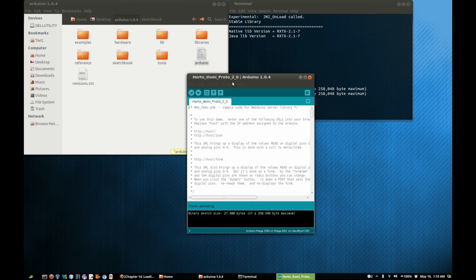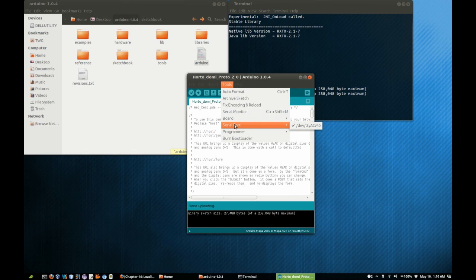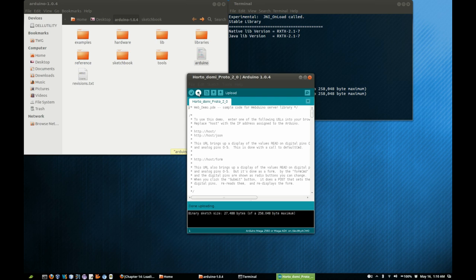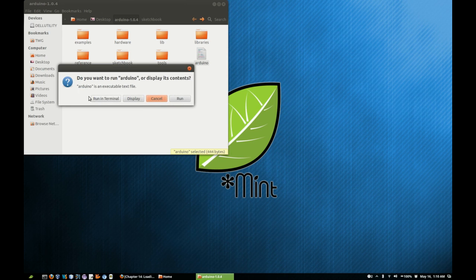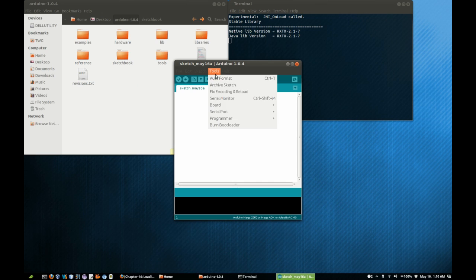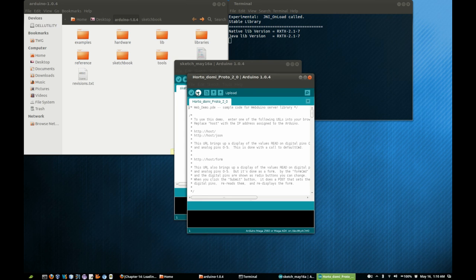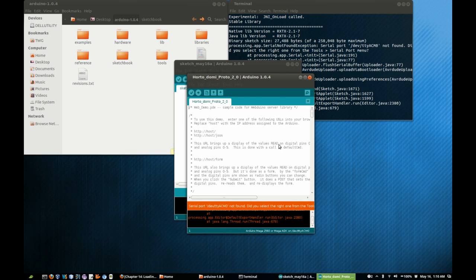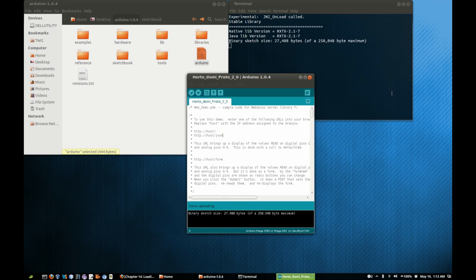Sometimes there's some weird business in this IDE. It's not always perfect when you're selecting the board, when you're selecting this port, and when you're compiling. And so sometimes you'll reach problems that really aren't very explainable. If you have bad problems with it, you can pretty much close the IDE and just restart it and go through the board selection, serial port selection, loading, and compiling again, and it'll usually work the second time. See, like this, something weird happened. Okay, so the code should be uploaded, compiled as a binary, and put into the EPROM on the Arduino.